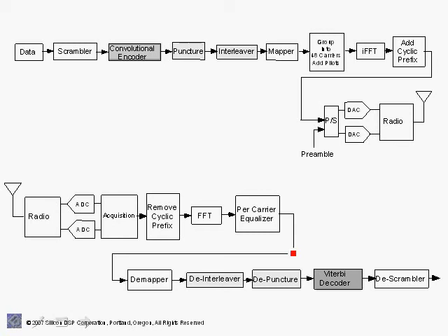So if we use the same power, or the regulatory constraints imposed by different countries, so you're limited by the power you use, then the addition of forward error correction coding with constraint length K equals 7 and using convolutional encoder, we can achieve about 5 to 6 dB of gain, which means that the receiver sensitivity is higher and we can actually achieve wireless communication over a much longer range.